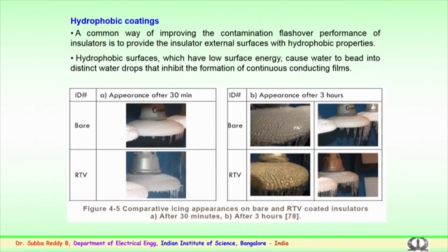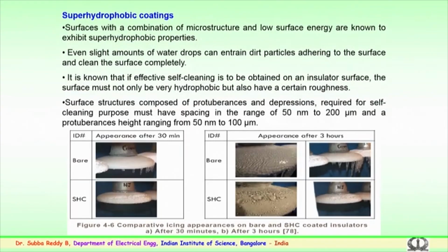Similarly, for RTV coated insulators, you can see the improvement after 3 hours. These are the comparative icing appearances on bare and RTV coated insulators for 30 minutes and for 3 hours. So, better performance is being noticed.